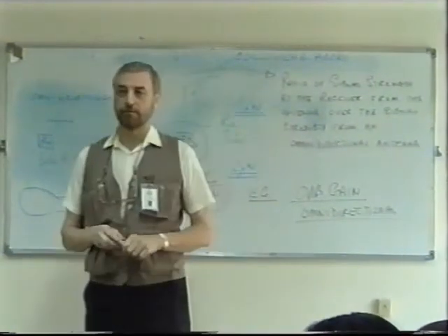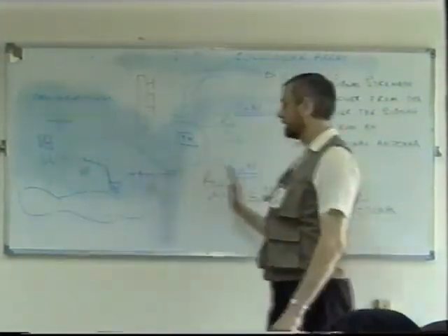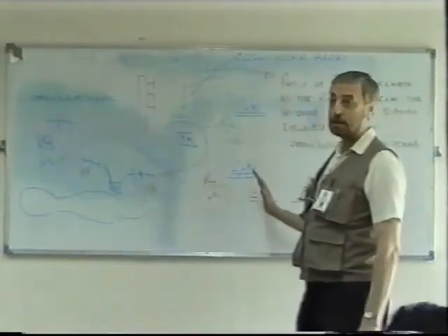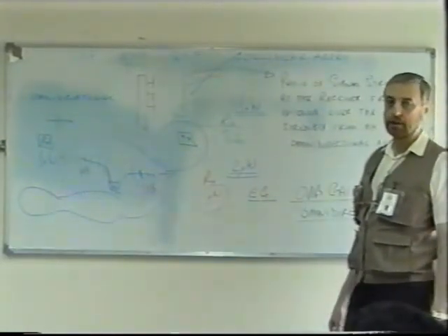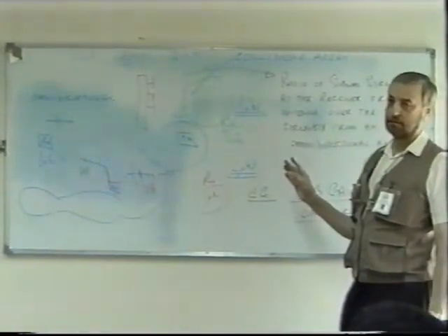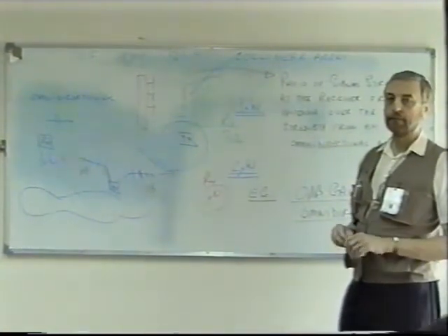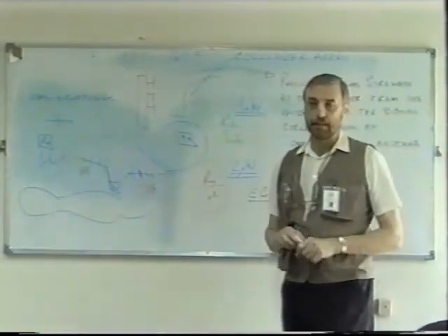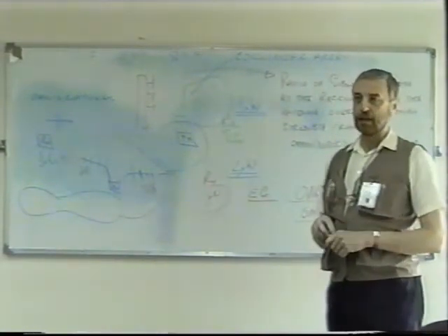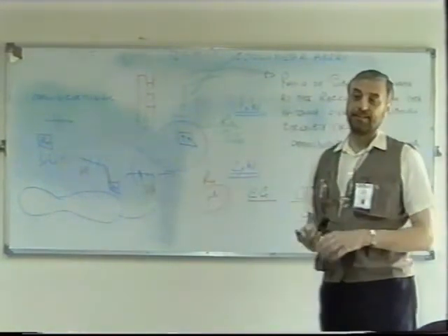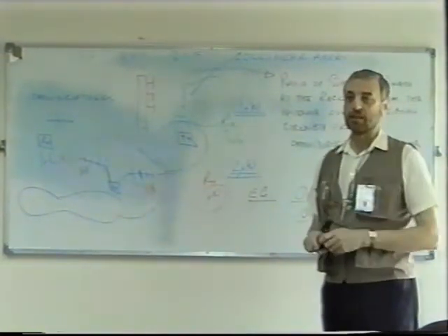We talked about distance this morning, remember? If the receiver is nearest to the transmitter, yes, of course, that's true. The distance the receiver is from the antenna, no matter what type of antenna and what the antenna gain is, the further away you are, the weaker the signal is going to be. But that applies no matter what type of antenna. So the effectiveness of the communication depends on the distance, the gain of the antenna, the power of your transmitter, the sensitivity of your receiver, the weather, based on the rain, and anything in between, any objects between the transmitter and receiver. So many things can affect your communication.